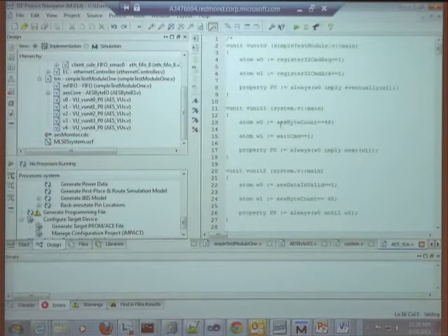The second one says if in the AES core, I read 48 bytes and then decrypt or encrypt those 48 bytes, and then I spit out 48 bytes. So this says after AES count equals 48, wait command. This is the next thing that should happen. You have to wait. The wait command has to be issued. So this is another assertion.